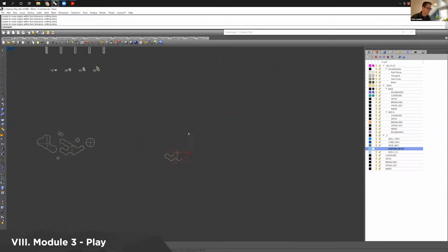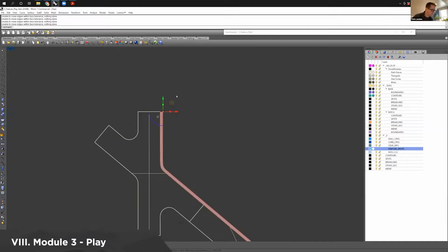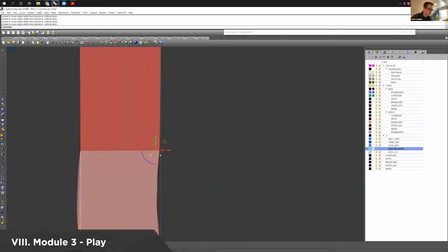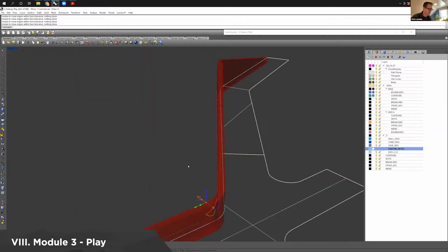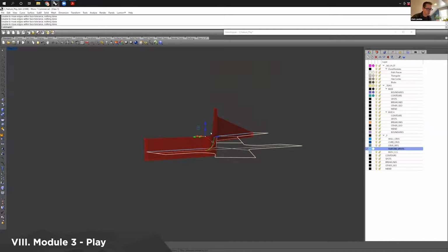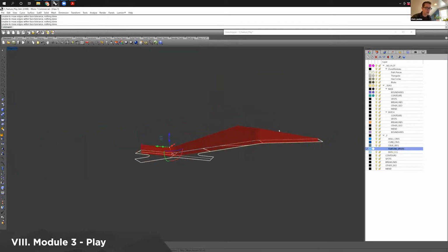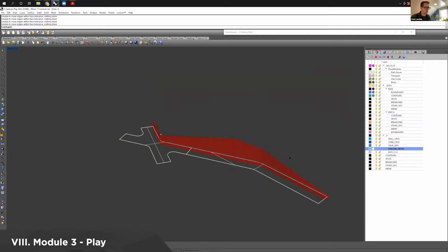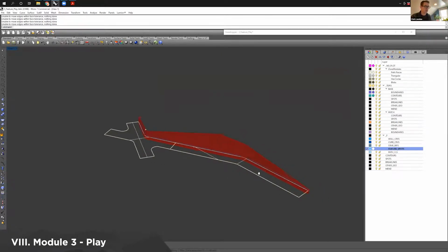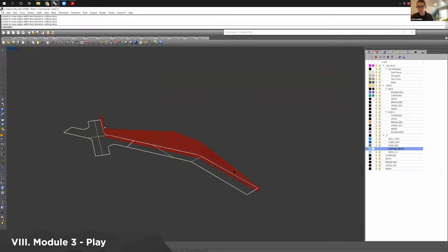and then we do an alt drag to get the point there. And I'm not snapping it, but because the tolerance is pretty close, it goes to there. And now I have a sort of seat wall condition here before it shoots up to the higher elevation and then comes back down to a curb height, right? Pretty awesome. Then you can plug these things into the topography, right? You can plug the curb, just like Ben was doing.